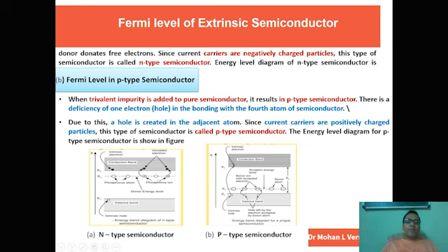So the Fermi energy level is shifted towards this at room temperature also. Whereas in a p-type semiconductor, in the valence band, some holes are there which recombine with some electrons, and one can say the probability of existence of electrons is shifted towards the valence band. So the Fermi energy level is shifted towards the valence band in the case of a p-type semiconductor.